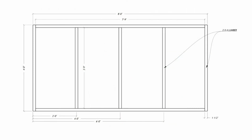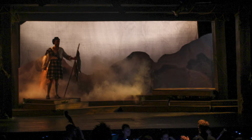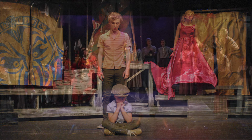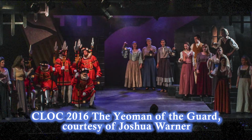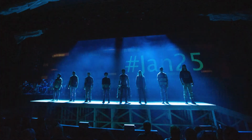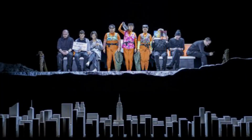Platforms are often constructed like very heavy-duty Hollywood flats and are used to create levels on the stage. Platforms can be constructed with wood or metal and are also frequently created in standardized 4-foot by 8-foot pieces. Often, platforms are used to elevate the entire stage deck, either for sight lines or to allow space below for automation, sound, and electrics cables and equipment. When the desired height of the deck exceeds the depth of the platform framing, it becomes necessary to build support structures that are both efficient to install and sufficiently strong to support the weight of scenery and actors.